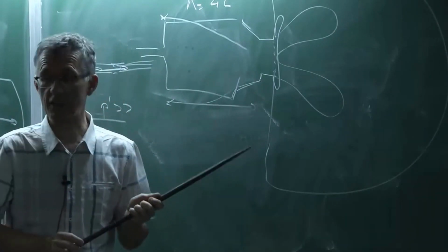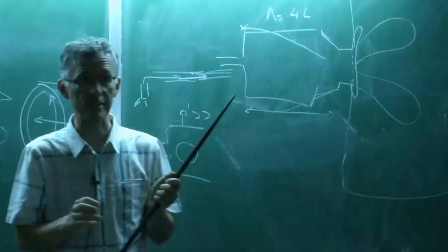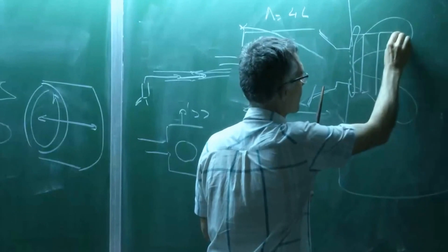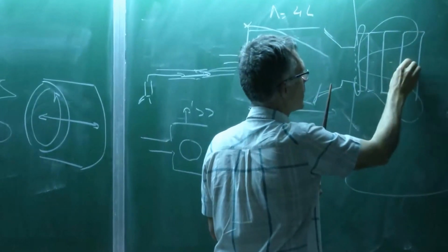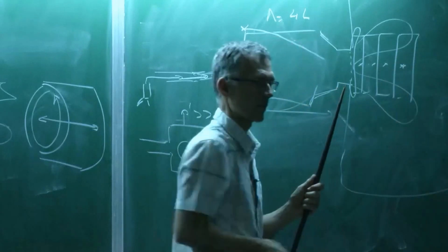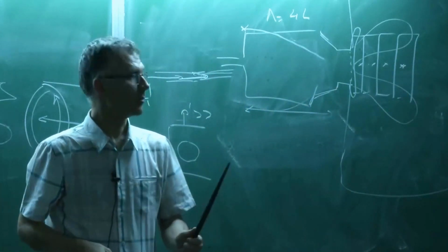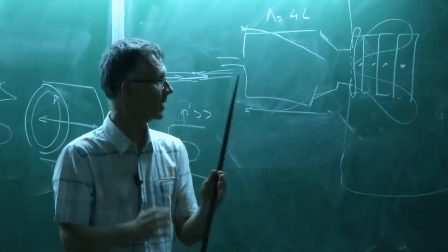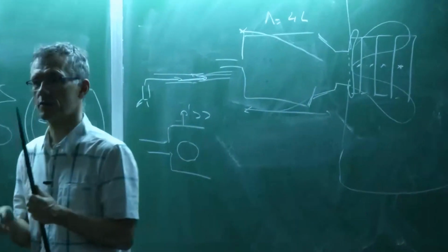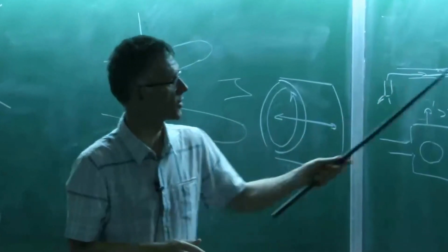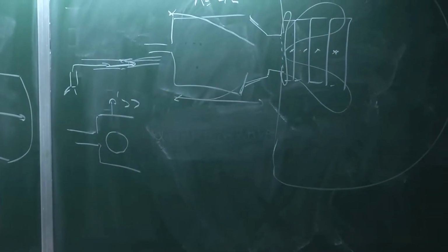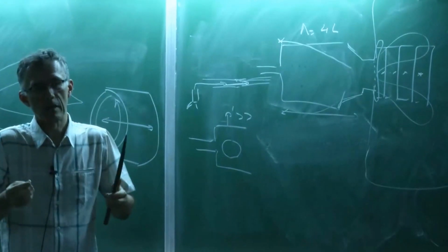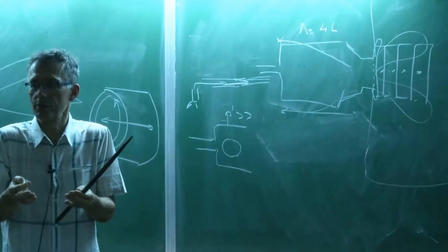If it's not like this, if it's not a compact flame, and for Siemens quite often it's not, it's a long flame, then you need to have multiple flame elements, and each flame element will have its own flame transfer function, which gets much more complicated right away. But for Siemens, that's what's happening, because in a Siemens flame, the flames are very long, and so you cannot assume that they are compact. So in that case, you need to subdivide the space into multiple flames, and that makes things more complicated. But again, considering the cost of this thing, because it's very cheap, it's still a good deal.